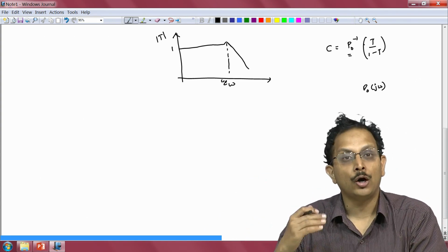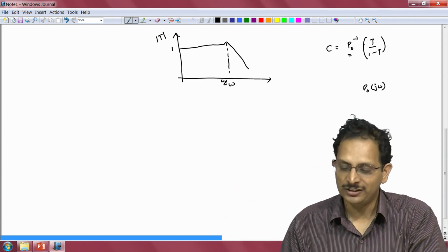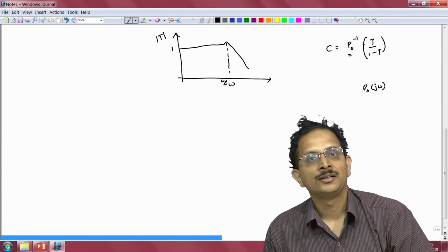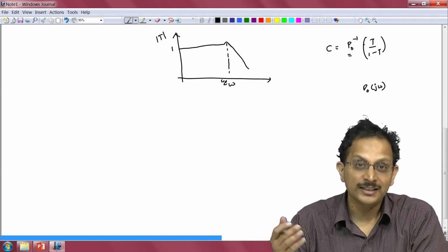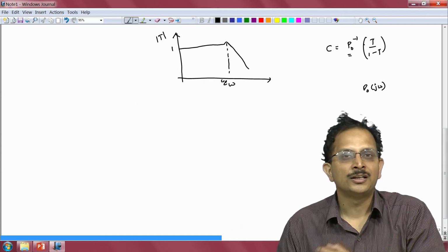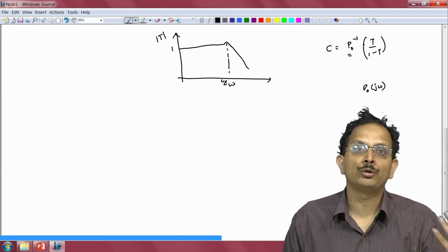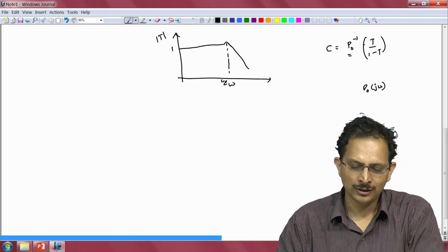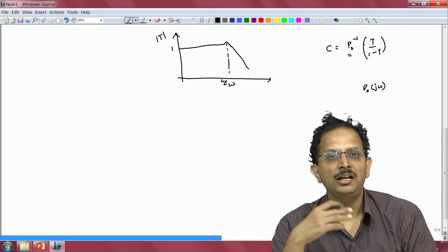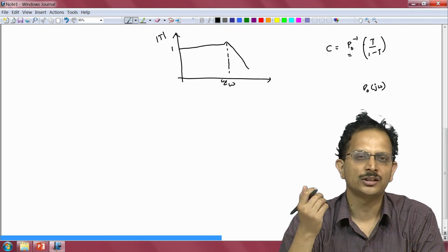So, therefore, the output of our controller will be of very large magnitude for frequencies that are well beyond the corner frequencies of the plant. And what that in turn implies is that the output of the controller is going to be very large, and that's likely going to saturate our electronics. Hence, for all these reasons, we cannot choose arbitrarily large bandwidths for the overall transmission function.